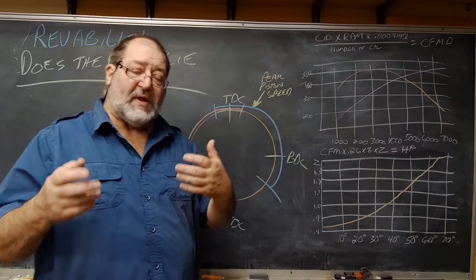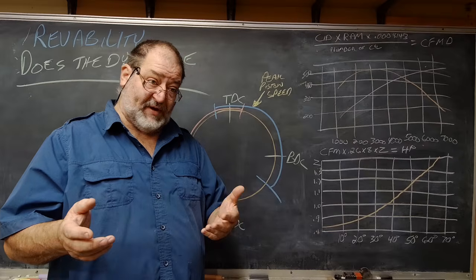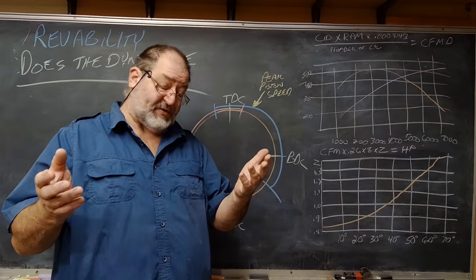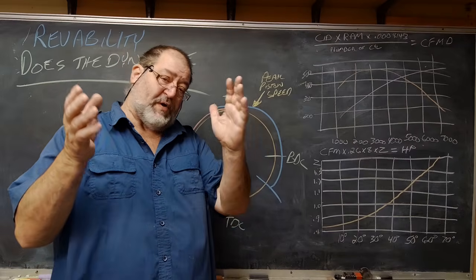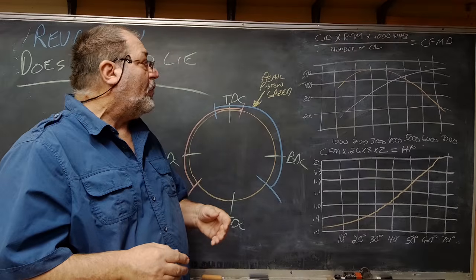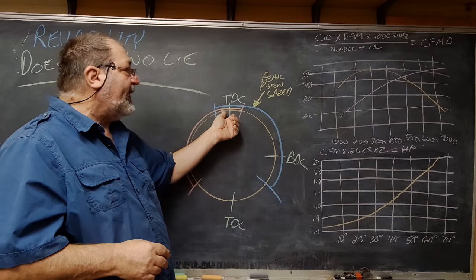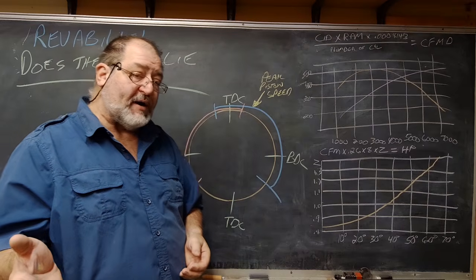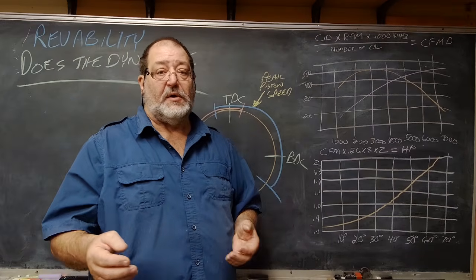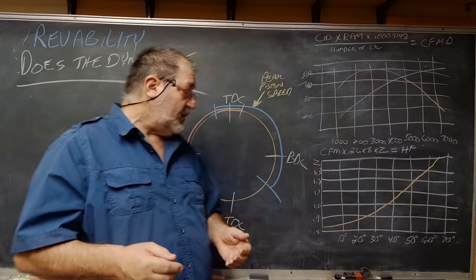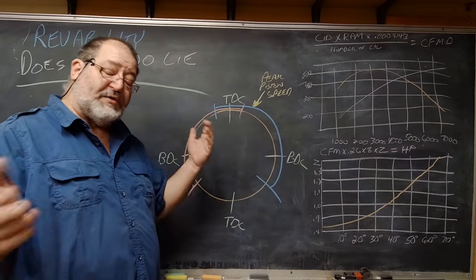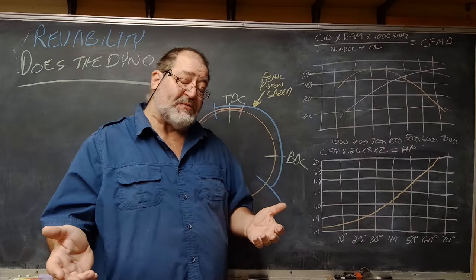Now, like I said, if we're working on a street vehicle, 2,000 to 6,000, that's our 4,000 RPM band. Well, you're working down here, then you really got to kind of watch overlap. Now, if you're working on a drag racing motor, those are easy. You can throw a lot of cam at it. Your events down here are going to spread way out just because the cam's bigger.